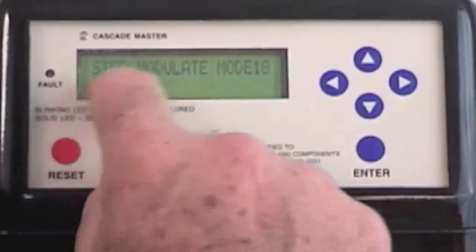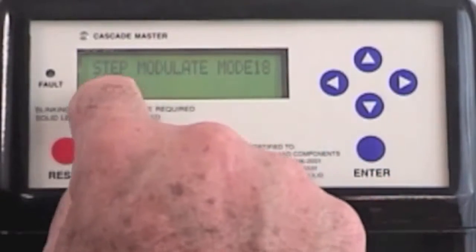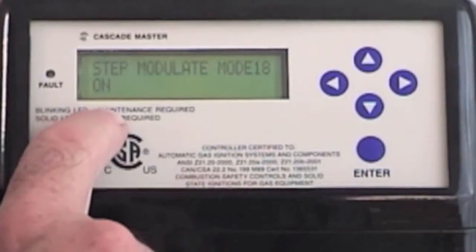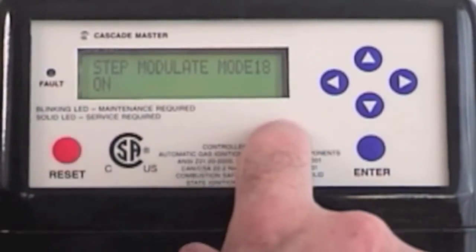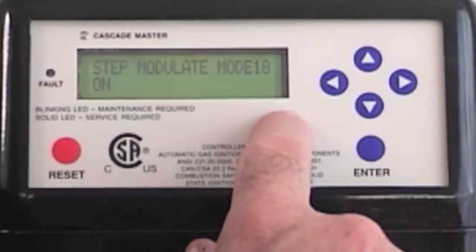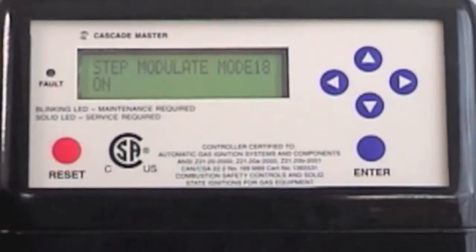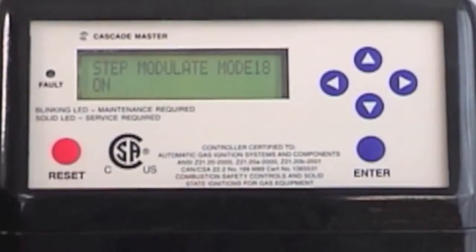The next one is step modulation. When this boiler starts on the heating cycle, it gradually reaches maximum RPM or firing rate over a 5-minute period. It's a stepped process. If I choose to make this boiler go to high fire immediately on the heating cycle,